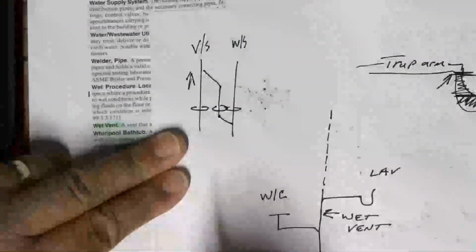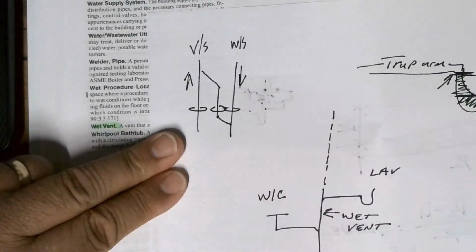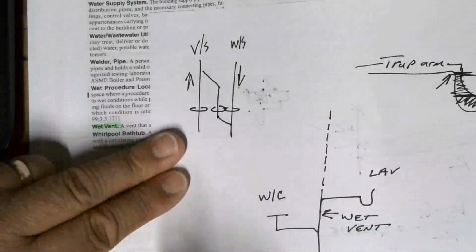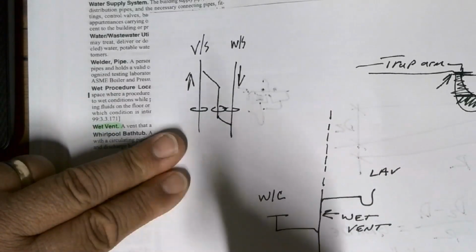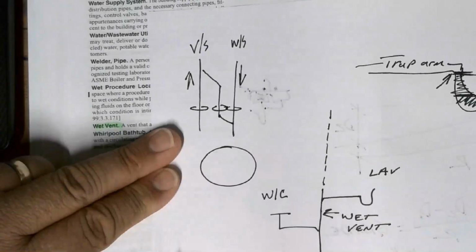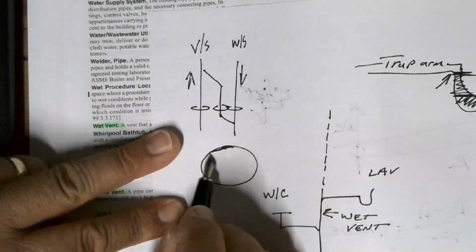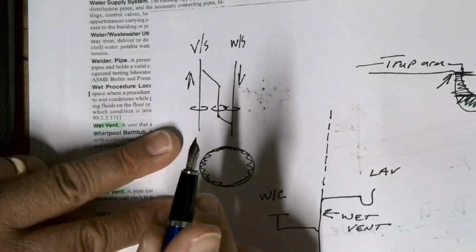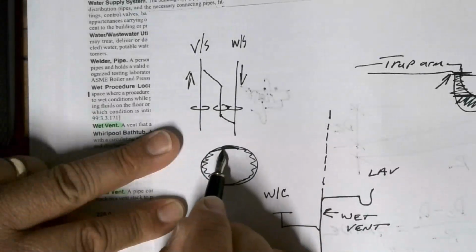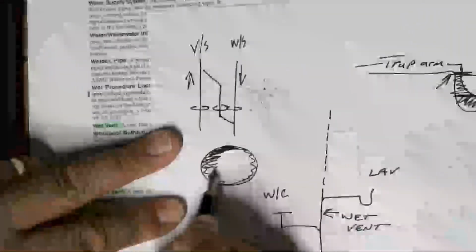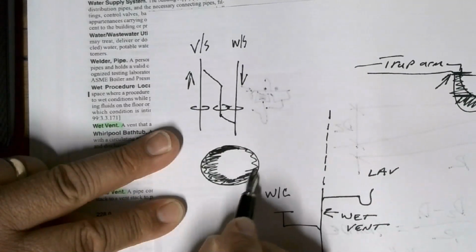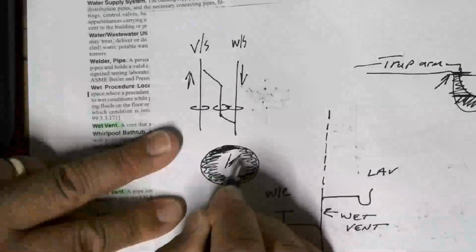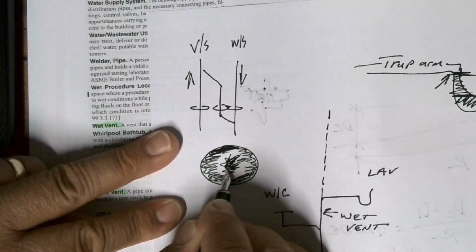So your vents are going up, right? The airflow goes up and your waste goes down. Let's say you got 20 floors, and that's nothing but a waste stack coming down. Well, in 20 floors, all that volume is going to create a solid plug. The waste will always come down and gravitate towards the edge of the pipe. It never flows down the middle. However, if you start to build up more and more volume, that speed and velocity coming down a vertical starts to separate off, and the liquid starts to go into the middle.